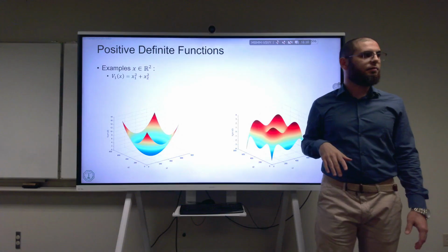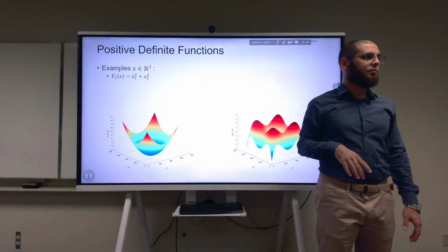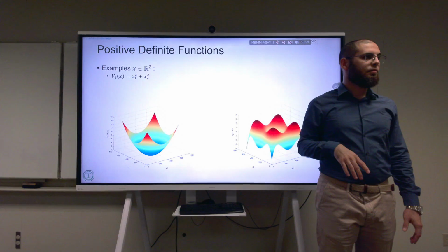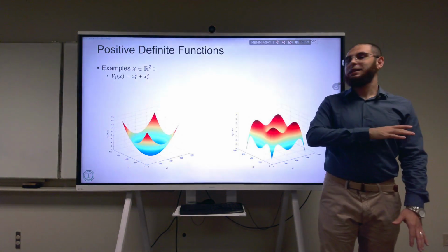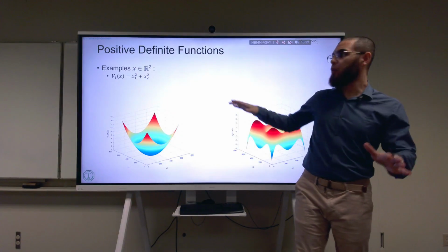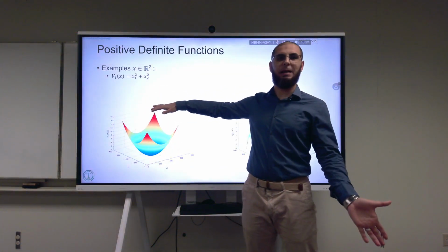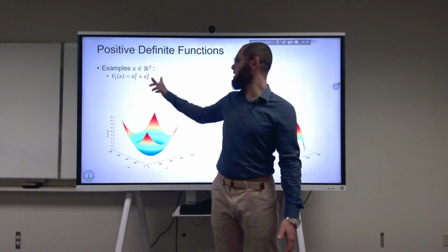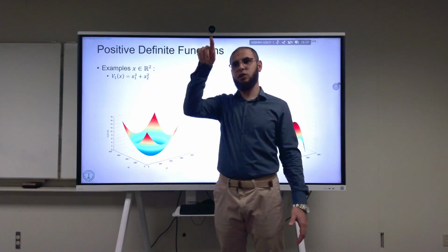So there are some rules to make this function. It's not just messy. It's not that we can do this function, this V, with any old thing. Usually what you're going to find, especially in control, the first choice is always the square function, the quadratic function, the parabola. If you took any course on adaptive control, this is usually the first thing you do: S transpose S. This is, by the way, x1 squared plus x2 squared; in general it looks like x transpose x, where x is a vector.